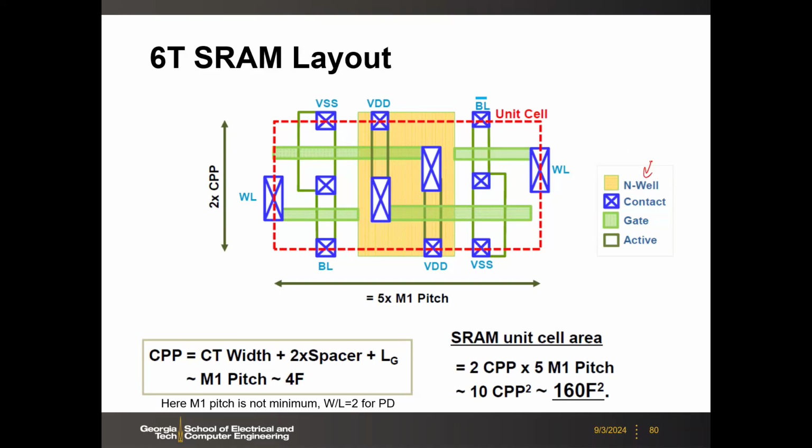So the PMOS is in the middle, and it's symmetric: 3 transistors to the left, 3 transistors to the right. And here, this is a PMOS transistor connected to VDD. You need to create this layout from the schematic. I think this is important for you. So this is a pull up PMOS here.